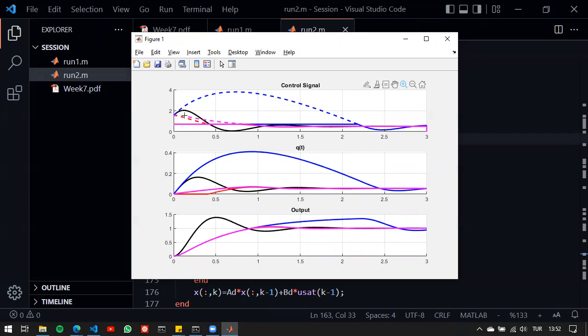We have to compensate for that, and there are two ways of doing that. We might just turn off the controller, switch off the integrator, turn it into a p-type controller during the saturation. We can live with that, you can see. Or we can just subtract the difference between the saturated control signal and the actual calculated control signal in order to compensate for this behavior here.